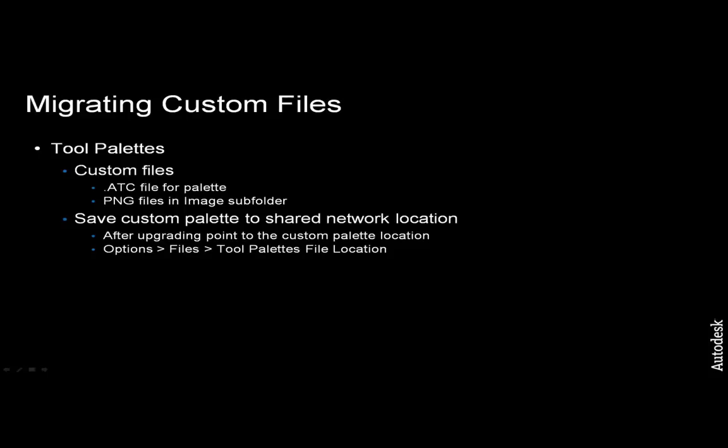To migrate a tool palette from one release to another, it is important to understand that there are custom files associated with each one of these tool palettes. In particular, the ATC file contains the information for the palette itself, and the PNG file contains the images, which are stored under a subfolder for that tool palette.